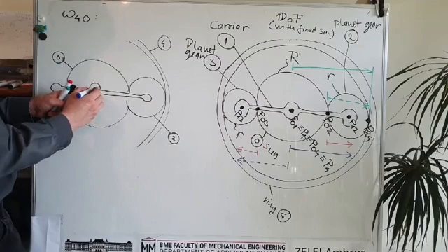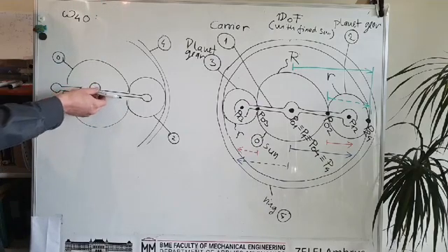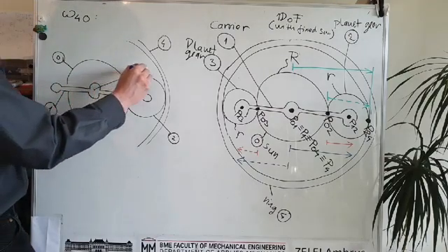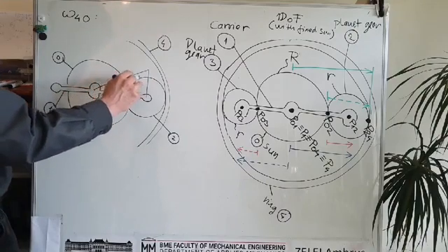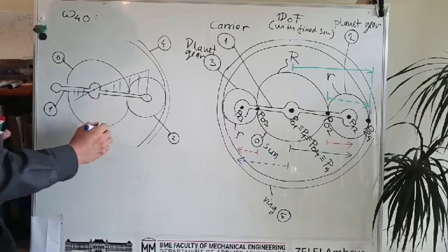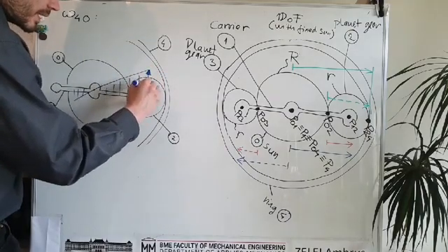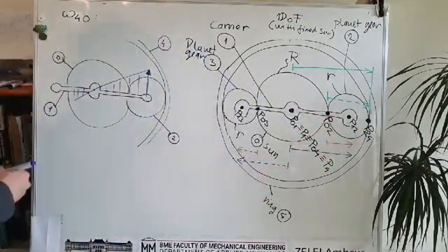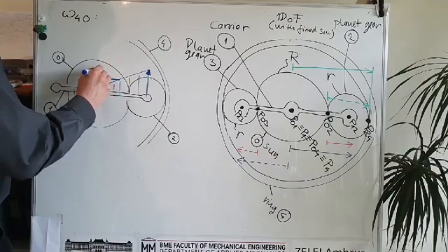If omega 1 is given, which is the angular velocity of the carrier, then I can simply compute the velocity of each point of this carrier, right? Here it will be negative, it doesn't matter for us. The important thing is that I will be able to calculate the velocity of this point here, and the slope is basically omega 1.